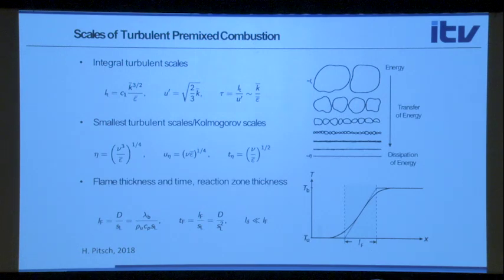And generally, the premix flame, which varies between the unburnt and burnt temperatures, has a thermal thickness across the entire temperature jump, but it also has a thin inner layer, L delta, that has thickness that's much smaller than the overall thickness of the entire flame. So roughly about a 10th of that thickness.